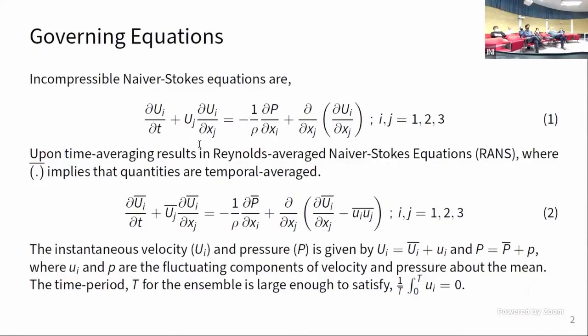But given that someday we have a big enough computer, we might stop discussing turbulence modeling, because at the level of Navier-Stokes, I actually do not need any model at all. I can solve the Navier-Stokes, which is the F equals ma equation, alongside the conservation of mass, and then for an incompressible flow, I just have the Poisson equation, and the system is complete for me to solve.